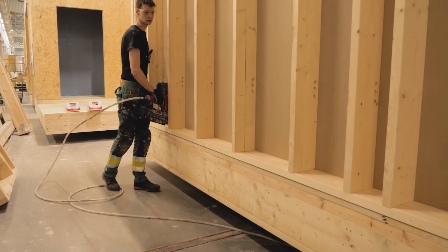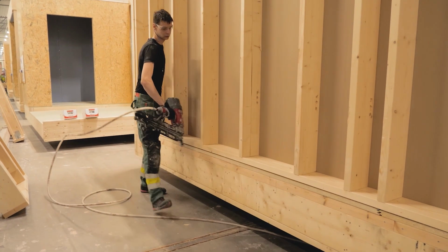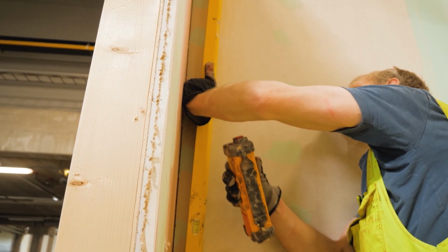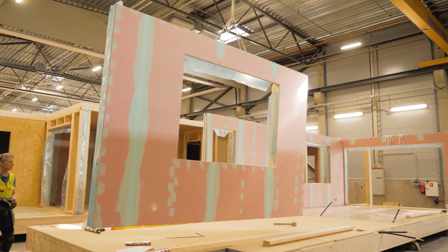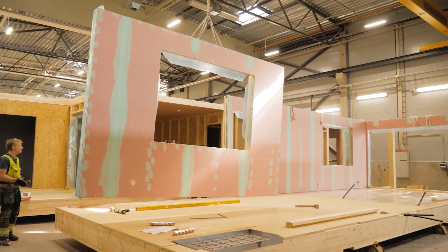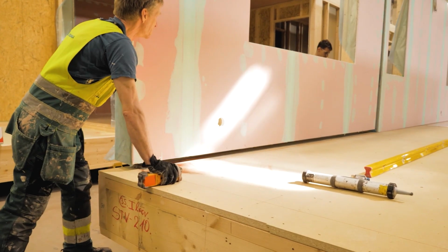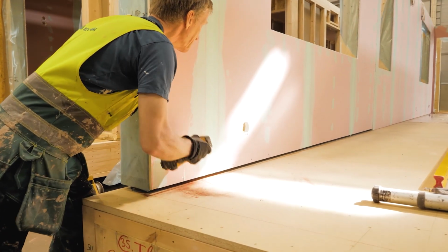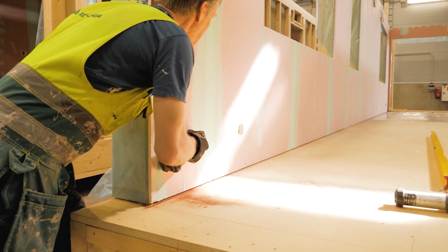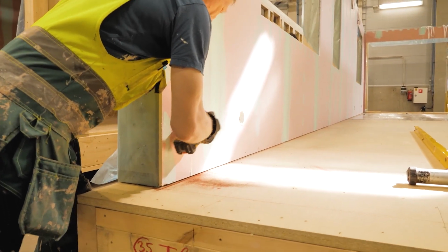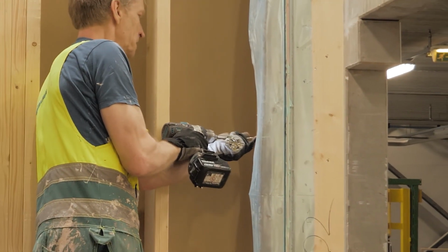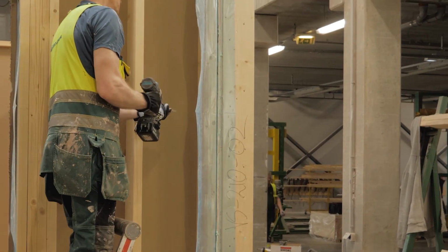The joining wall elements are fixed with screws or nails according to the standard solution provided by the company or drawings. When installing the elements of the external wall, attention should also be paid to the placement of the vapor barrier film. Depending on the project, there may be several solutions, but it is important that the vapor barrier film forms a hermetic union with the floor panel, adjacent wall and ceiling panels to secure the module from any moisture damage.